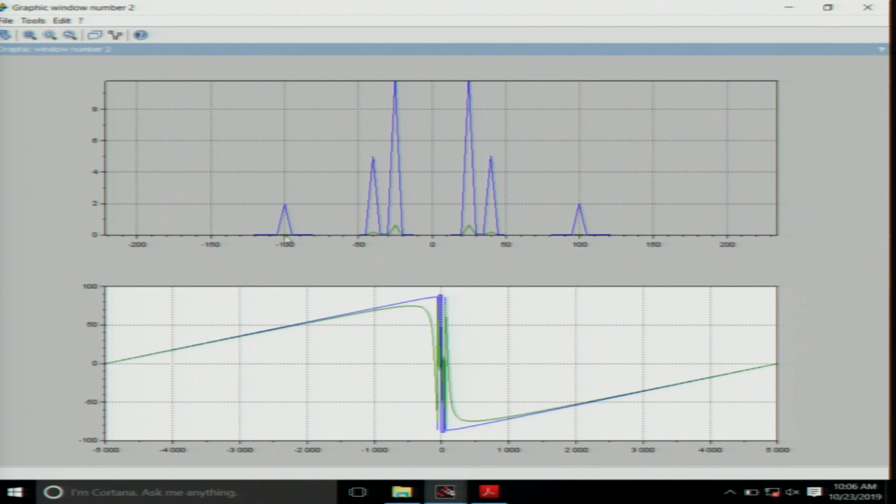Now, if I change the time constant of this, of course, you will find that the ratio of the input and output will change. So, the important takeaway is that you can get the transfer function at these frequencies by taking the ratio of the input and output at these frequencies. And how do you get the input and output at these frequencies? You can actually numerically get the Fourier series components. If you know it analytically, of course, you do not have to do all this, you can get it analytically as well. The phase components also can be obtained in a similar fashion.